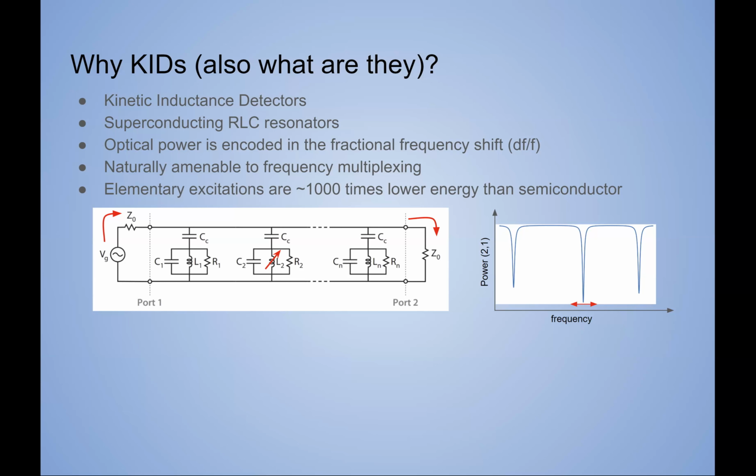How much does the quality factor of the resonators matter to the real system? It matters a lot, actually. Here I've drawn a very idealized system, but you're always trying to design resonators with the best quality factor, just so you can cram more of them into a given bandwidth. And the problem we actually have a lot of the time is that we don't quite get these capacitors correct, and so the resonant frequencies are off. It's a very simple sounding problem, but it's really hard to correct because you then don't know which resonator is which if they get close together. So yeah, Q is pretty important.